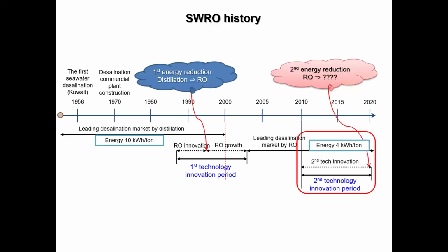But now, with energy, oil is very expensive, right? You can see the oil price significantly increased. Distillation is no longer cost effective and reverse osmosis is better, because we can achieve 4 kilowatt hour per cubic meter for water desalination, at $1.2 per cubic meter.